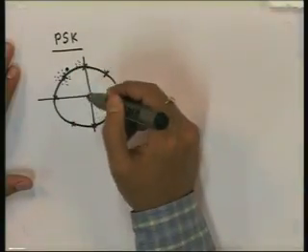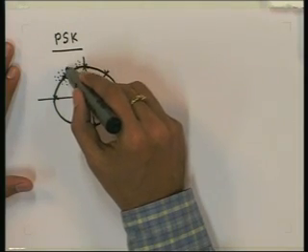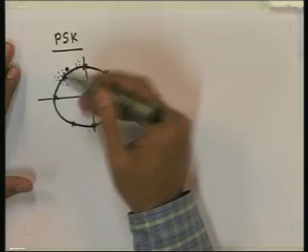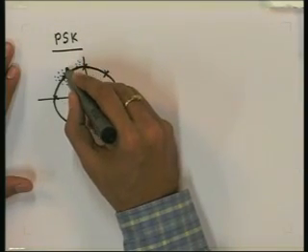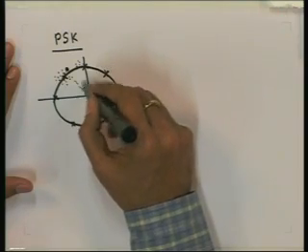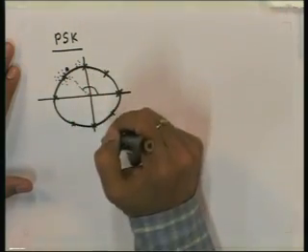So, instead of taking the distance or instead of taking the correlation and then equivalently finding the distance and comparing, we can simply find the phase of this point and see which is the nearest point here in terms of phase. If the phase of this here is this, then this phase is nearest to which phase of which signal here, which point here, that we have to see.